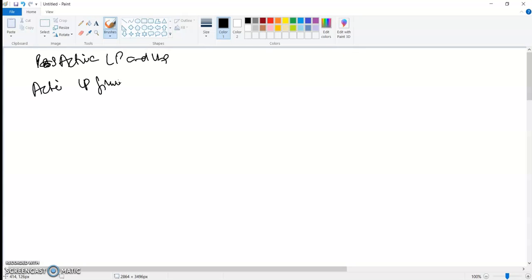As stated in the last session as well, the difference between active and passive is that active is with op amps and transistors, while passives are with just resistors, inductors, and capacitors. Active allows you to provide a gain, passive doesn't provide any gain. Active is good in terms of the loading effect, as your output circuit is basically isolated from the input circuit. There are three major key differences that decide to use active filters rather than just passive filters.